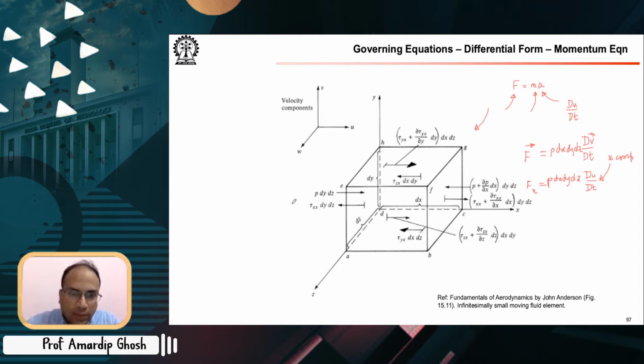Okay, so anyway, as you can now see, last time I emphasized that the normal forces, see, it's not just p. P times the cross surface area creates the normal force, but you see that we also have these tau terms with the same subscripts. You remember from last lecture that the second subscript tells you the direction of the force. The first subscript tells you the orientation of the plane on which the force is acting. I am saying these things many times because you will perhaps appreciate it eventually, that sometimes some of these things become a little confusing.